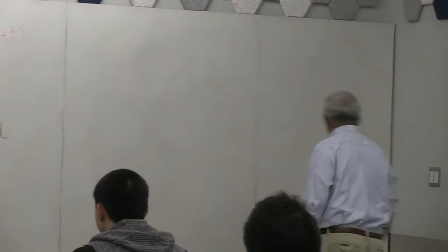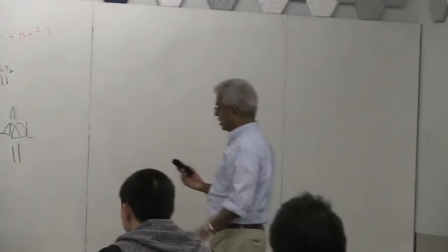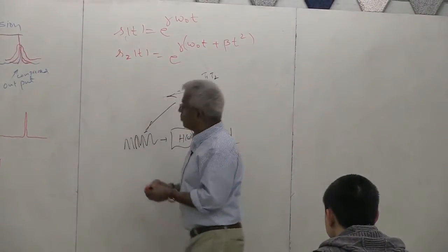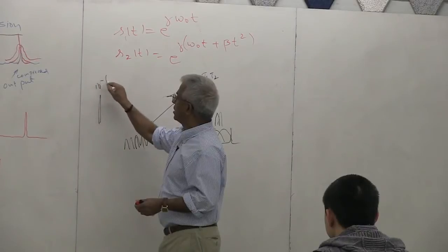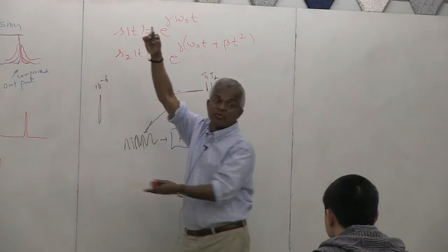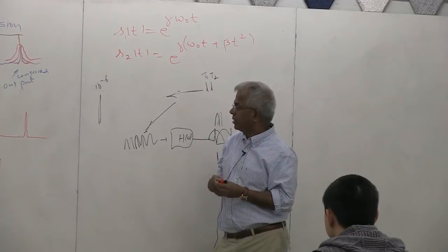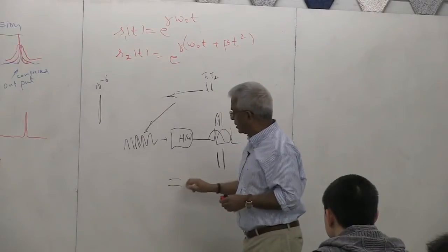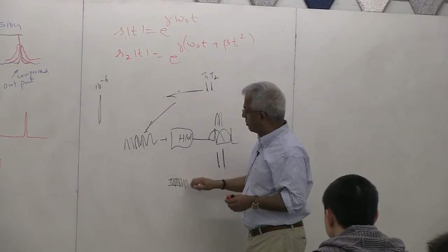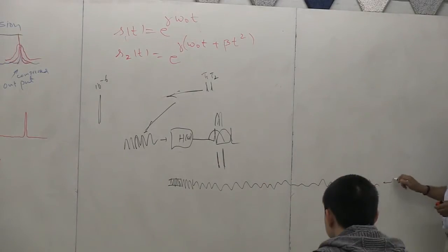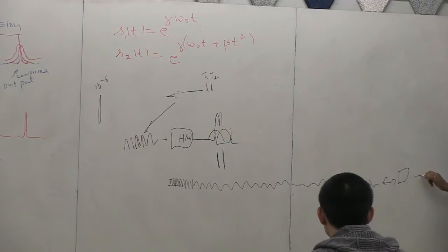It's very important. But you may say, why don't you transmit a very short pulse? That's impractical, because if you want to transmit a pulse of only duration 10 raised to minus 6, its amplitude will have to be very high. So what generally is feasible is to transmit a very low amplitude pulse for a long time. But then if you can pass it through a filter and make it look like this, that's what we mean by pulse compression.